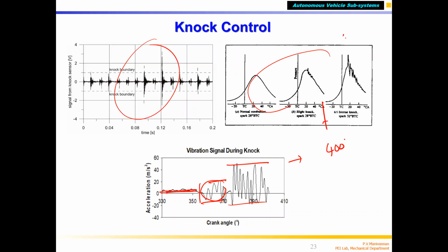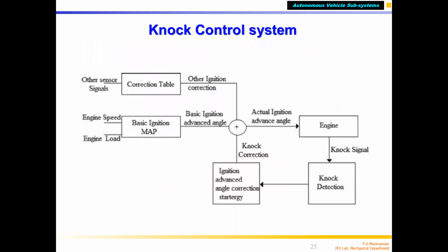Of course, they put water cooling. Water circulates inside the in-cylinder pressure sensor, correct? To cool this sensor, otherwise they fail. But there are now high temperature sensors, so there's no need for cooling, correct? In-cylinder pressure. These are washer type piezoelectric materials, so they can withstand up to 400 degrees. Okay, there's no problem.